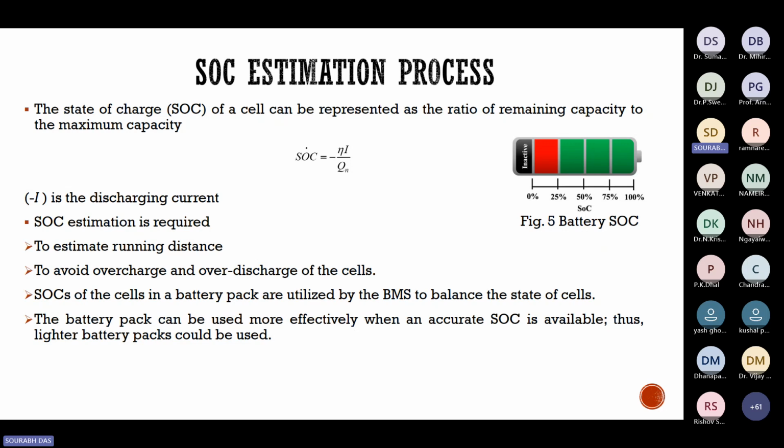After that, 2.8 volt to 4.2 volt is the 0 to 100% SOC, and generally the 0 to 20% and 95 to 100% ranges of charging the battery mean more time is required. I will explain this later.